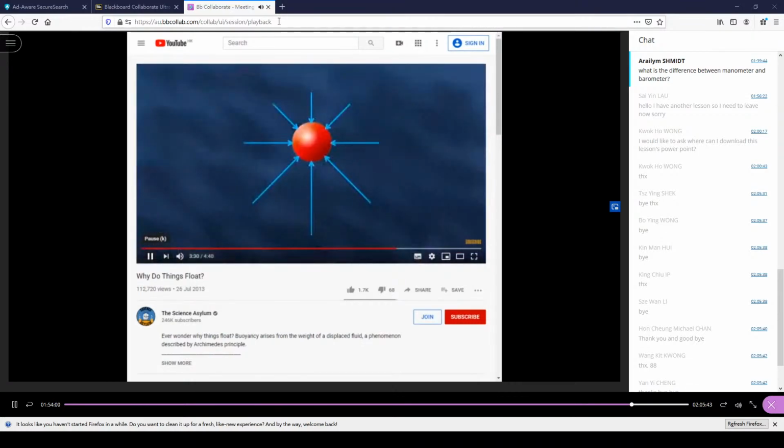Okay, back to the ball. We can add all these little forces together, but we have to be careful about direction. So we'll split them all into 2 pieces. A quick look at the horizontal pieces and you can see they all cancel each other. The vertical ones don't cancel because they're bigger on the bottom. They push more up than they do down. So adding them together results in this, which is called a buoyant force.